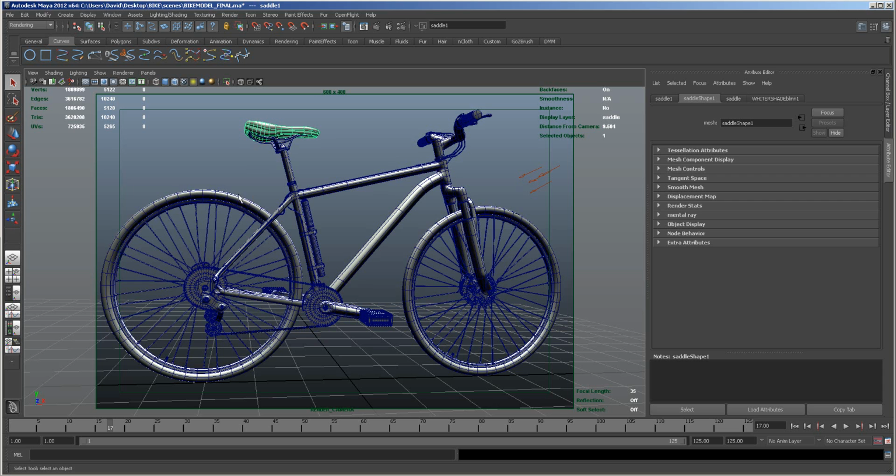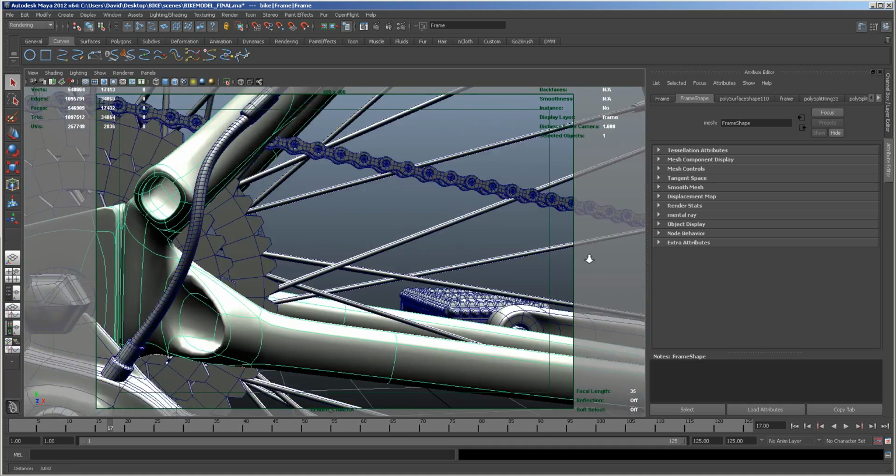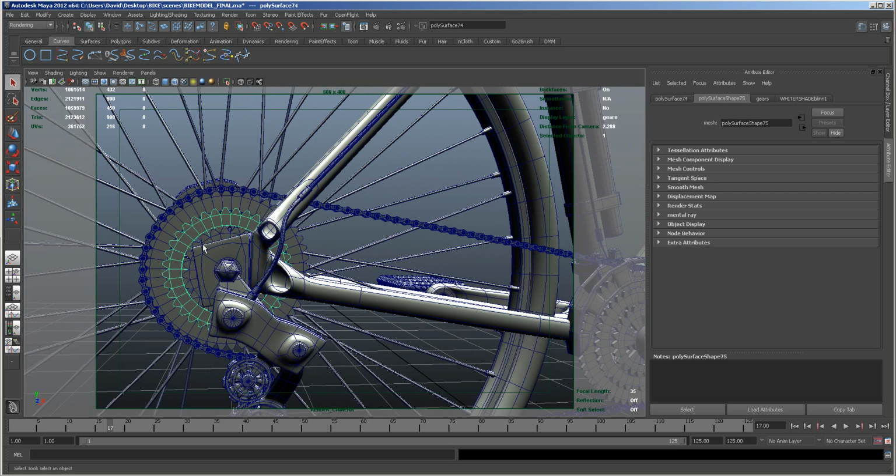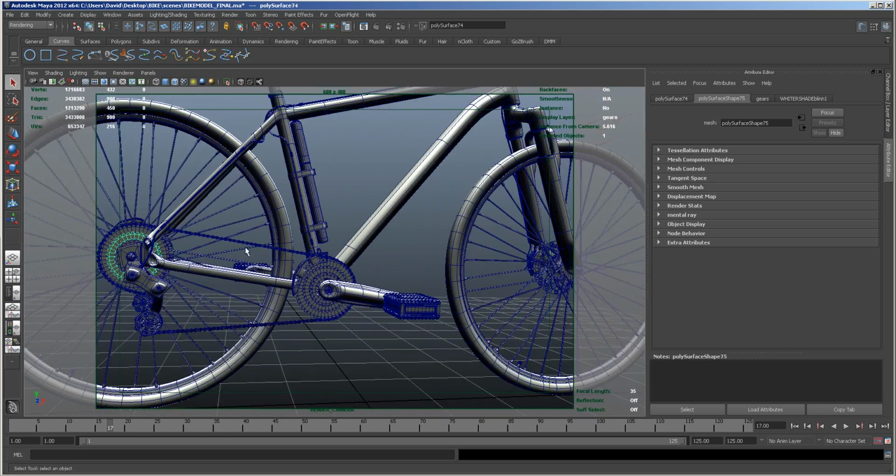When we're creating the texture map, unlike when we're projecting, we have to lay out the UVs, and it's good policy to lay out the UVs, especially for this training course, because it will give you more practice. So if you want to try laying out all of these on your own once you've learned the techniques, that's really good. Also, things like the gears down here, which we're just going to apply a material to, if you want to actually UV lay these out, then you can add things like oil effects and things around here, which will look really good. So that's all of that.